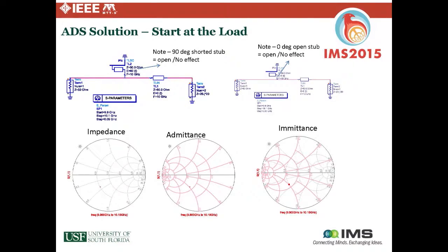Okay, and this is just another example with a shorted stub. It's just a different solution. The shorted stub is going to bring us the other way, so we have to come to this part on the G = 1 circle, so that, if you remember one of my earlier charts, the shunt inductance is going to bring us up this way to the match.